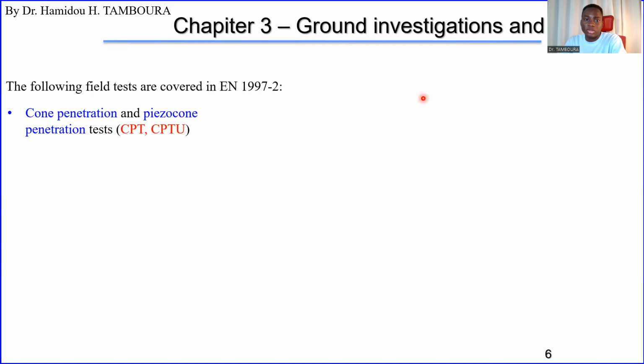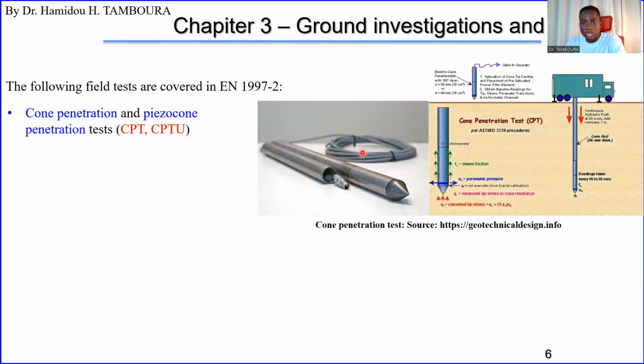We have cone penetration and piezo cone penetration test, CPT and CPTU. The difference is very simple. In CPTU, we also measure the water pressure. That's the difference.